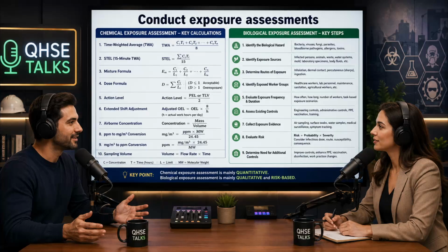Exactly. Now, the defining metric of an IDLH value is that it represents a concentration from which a worker could escape without injury or irreversible health effects within a 30-minute window if their respiratory protection completely failed. Wait, hold on. If I'm a worker and my supplied air respirator gets cut, does that mean I have a 30-minute window to finish turning off the valves and pack up my tools before I evacuate?